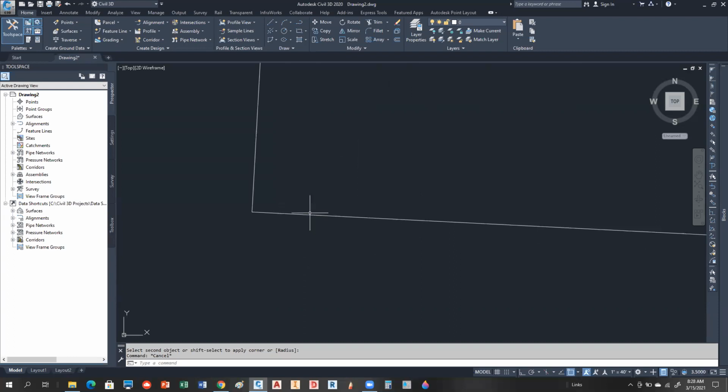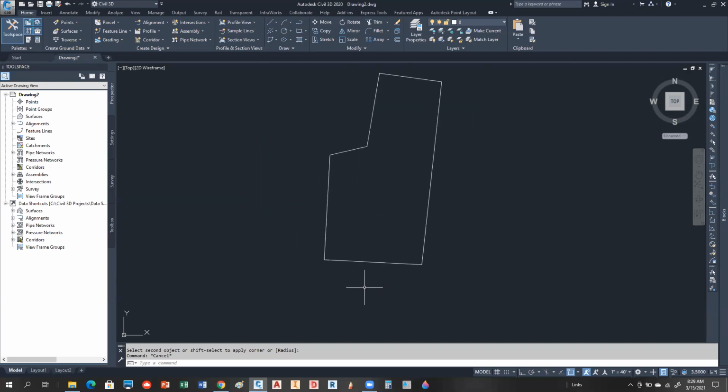Okay, make sure that you close this. That line, that distance there was only to the halfway point. So if you just fillet that with 0 radius, that should connect those two guys up.